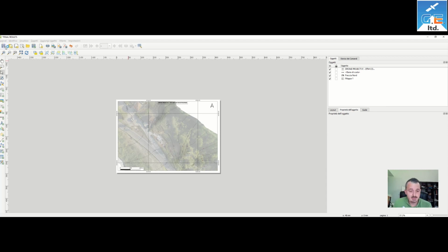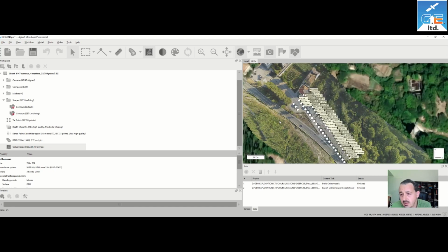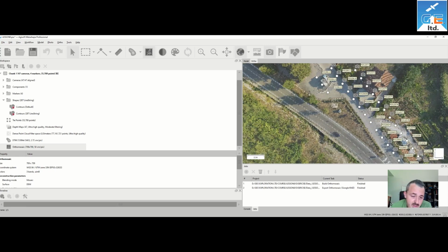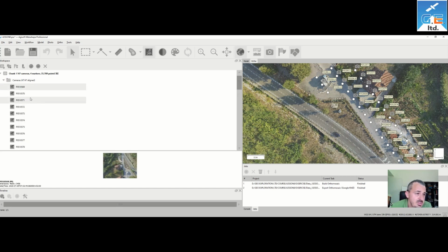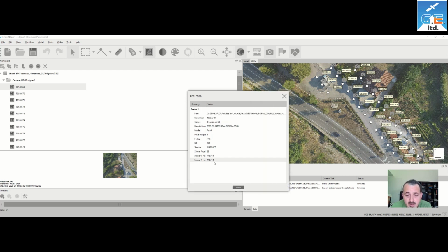So that's clear. The software that we are using in this case, for example, Metashape, automatically does the auto rectification, because if you remember the first lesson, when we see the parameters of acquisition, and we see, for example, how the single shot was acquired, you remember that we have a correction to do by pitch and roll.